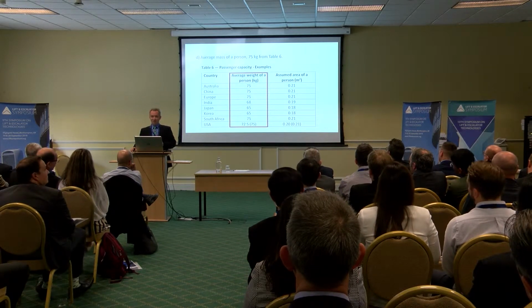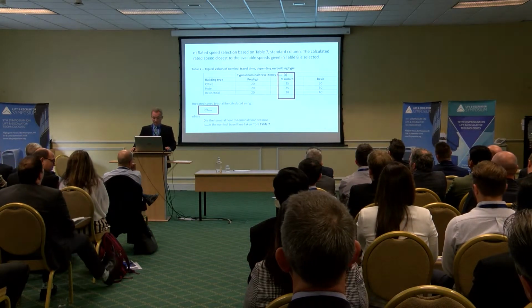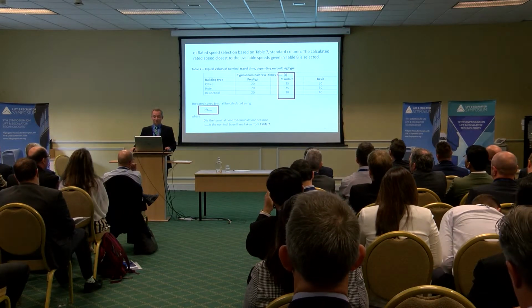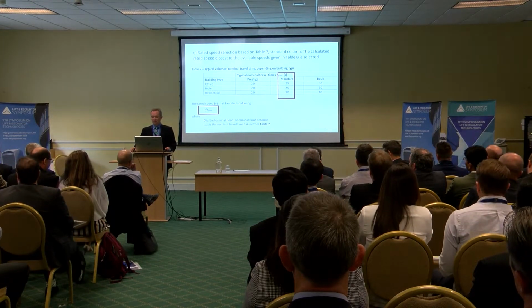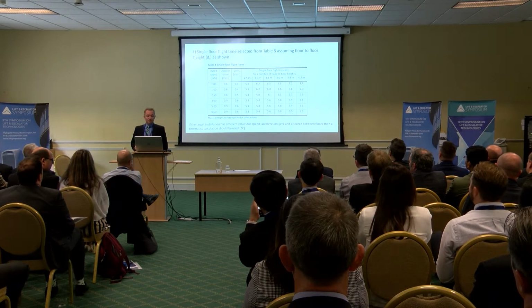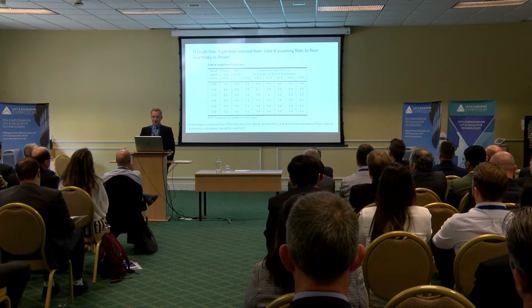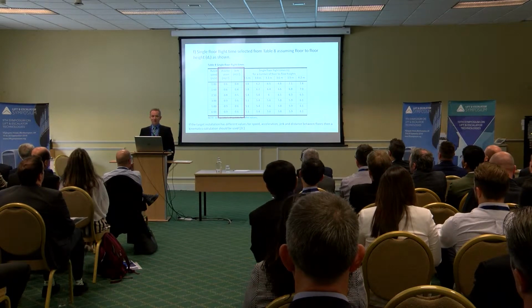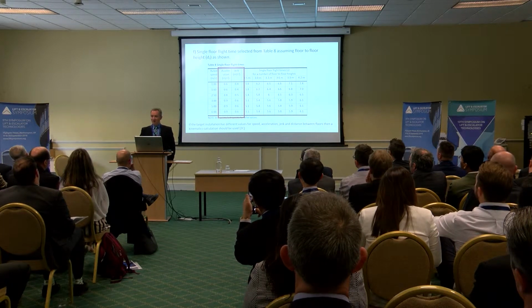And if we're going to account for mass as well, we wouldn't do mass only, but if we account for mass as well, we'd have that. Then we've got to decide what our lift speed is, and that's this table here. And Gina asked for the standard numbers, so that helps us decide what lift speed is. And then we need to talk about flight times, and this is a flight time table. I'll just take a little side discussion about acceleration and jerk. Those who are really into traffic analysis will note these are quite low, aren't they?